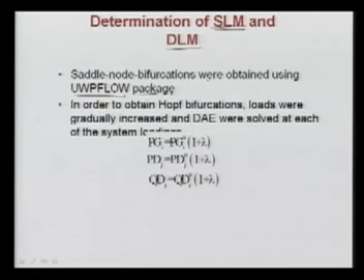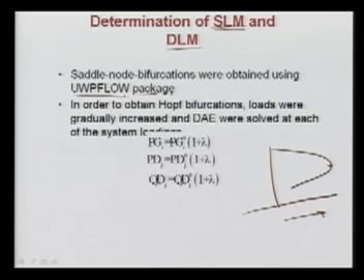As you know, it works on the continuation power flow method. By changing the load parameter, you can get the complete saddle node bifurcation, and then get the margin from the starting point. Suppose lambda is changing here; from here to this point you get how much loading there is, so you directly get the loading factor and can say you have this margin in the system.